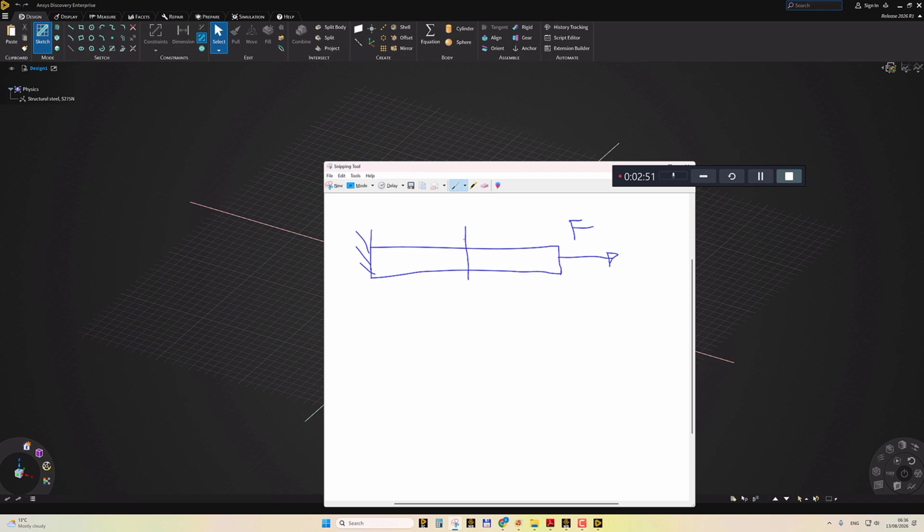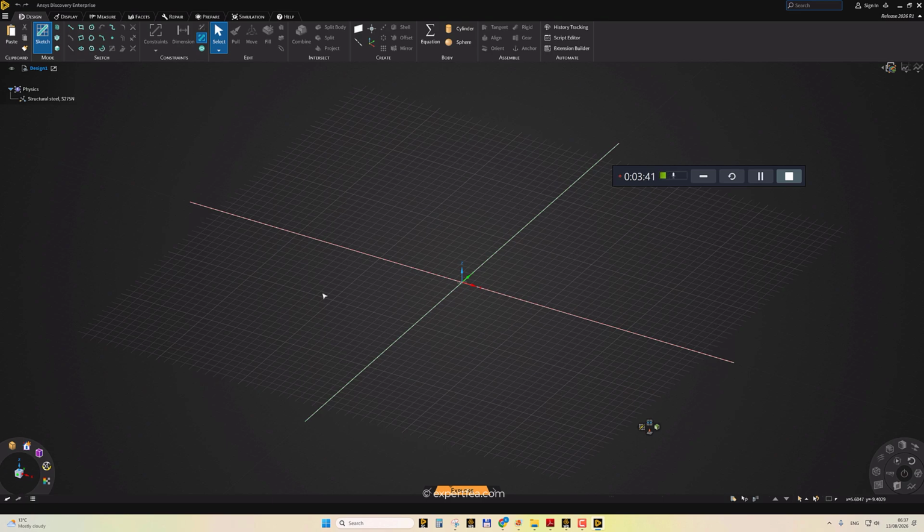Here there will be an area, and we will need to find the stress, which is force divided by area, then the axial displacement, which we will call delta L. The formula for delta L you might remember from strength of materials: force multiplied with length over Young's modulus multiplied with area.